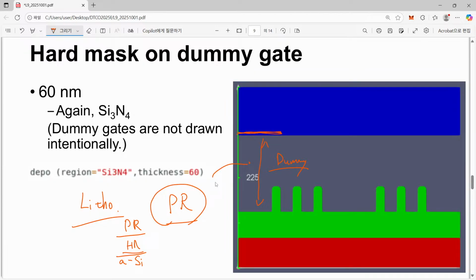But even in that case, we considered the silicon dioxide sidewall not strong enough to be used for our patterning. Eventually, we had to introduce a hard mask layer. So we first transfer our initial pattern into the hard mask, and from the hard mask the later pattern should be made. Quite similarly, even in this case, we have to introduce a hard mask.